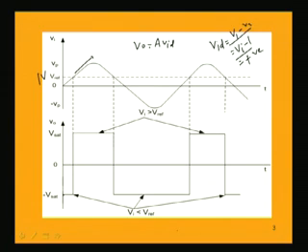So, it will be jumping from the positive to the negative saturation voltage as soon as Vi becomes lesser than V reference. That is why it is jumping to the negative. Again this will continue till the point when Vi is still less, and as soon as it is greater than the reference voltage, V reference, it will again become positive V saturation.